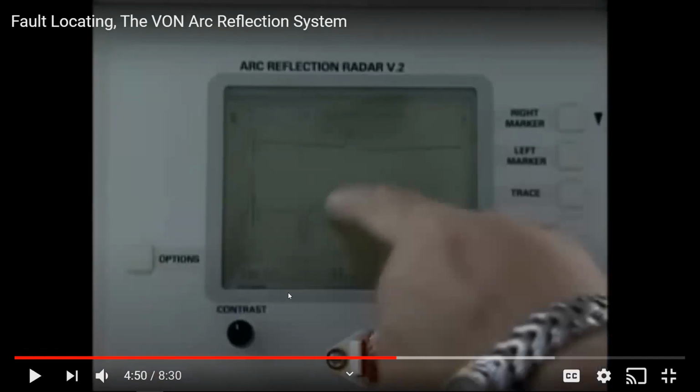Okay, so now he has introduced voltage onto the cable. All right, it's thumped one time, and you'll notice on the screen right here, this was the full span, here to here, and you can move these hash marks to get a measurement. All right, now the thump gives a picture for it right here at the bottom, and you'll actually see this inversion right here. You see it? You move this cursor over to here with these arrow markers. You move it right over to the leading edge of it, and that's going to tell you a footage on the bottom to the fault.